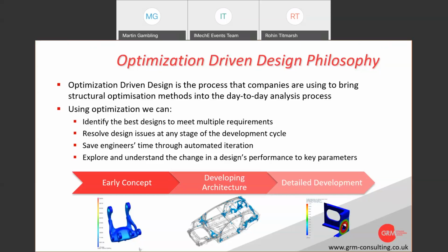Often if you think of designing a part, be it a structural problem, you can look at it, think of the loading going on and work out the load paths and have a fairly good idea of the structural layout. But when you have, as you do in automotive applications, dozens of load case requirements, finding that best compromise is where mathematics and optimization algorithms can offer you that bit more. So considering those multiple requirements.